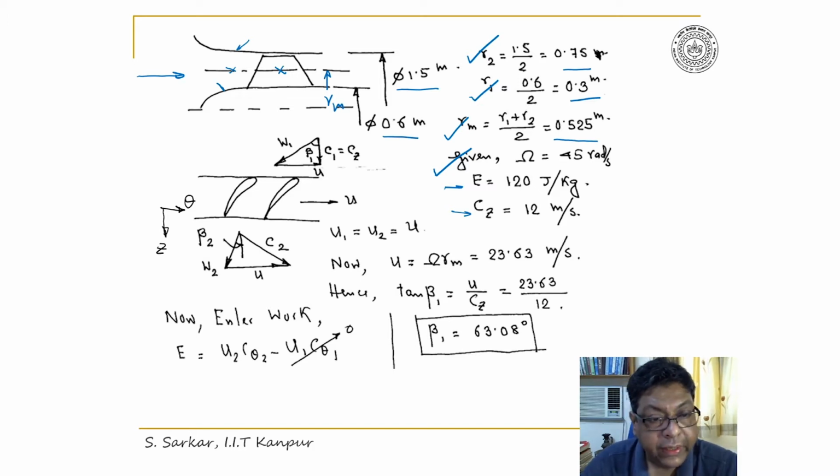Now, if I take the circumferential section at the mean section and stretch it on the plane of a paper, I'll get the aerofoils. These are the blades, and since these are pump impellers, the flow will decelerate.